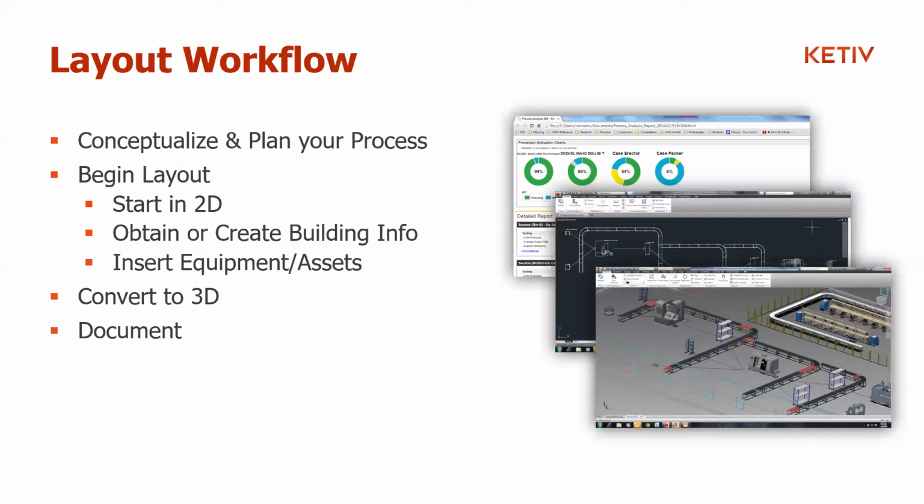You'll have choices on where to create your drawings. You can do this in Inventor, right? Or in AutoCAD, and in some cases, both. AutoCAD lends itself to the architectural environment. So if you have to deal with municipalities or anything like that, it makes sense to create architectural construction drawings, things you can send to municipalities, in AutoCAD. Okay. If you need a live active bill of materials for your drawings or your engineering data, you might want to document that in Inventor, because that's one of the things it does. It gives us a good, nice, clean list of bill of materials.